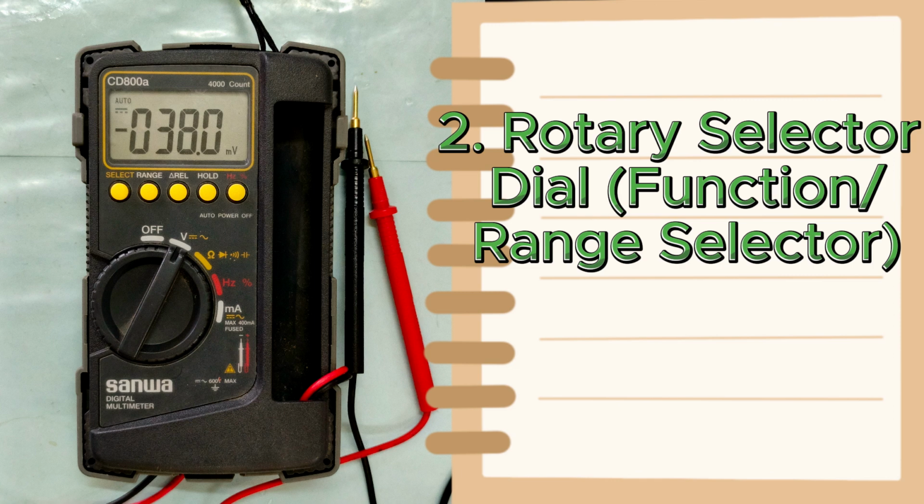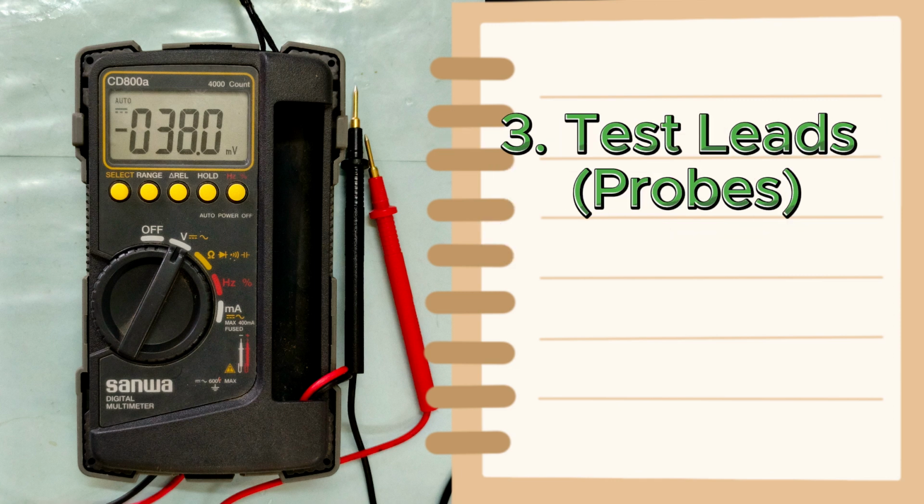Resistance, ohm, measures resistance in ohms. Continuity test: emits a beep if a low resistance path exists. Diode test: checks the voltage drop across a diode. Capacitance, nF, μF, mF, measures capacitance. Frequency, Hertz, measures signal frequency. Temperature, degrees C or degrees F, requires a thermocouple for temperature measurements. Impact: ensures proper mode is selected for accurate and safe measurements.